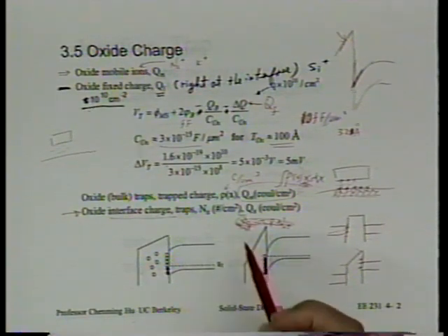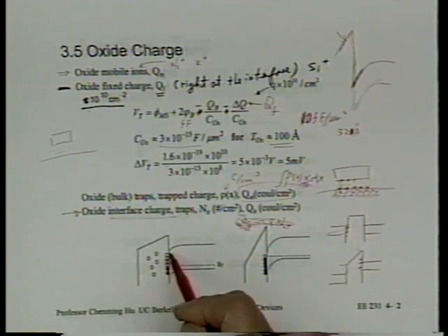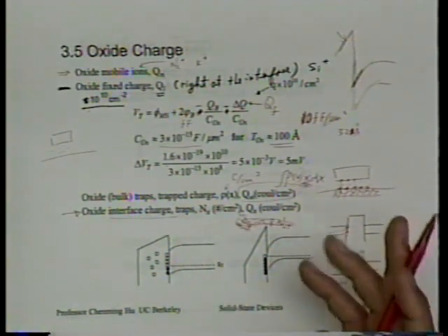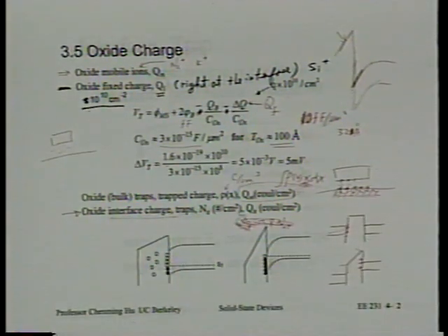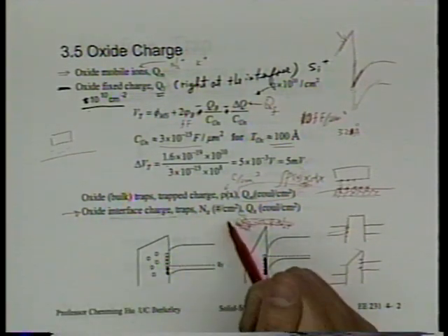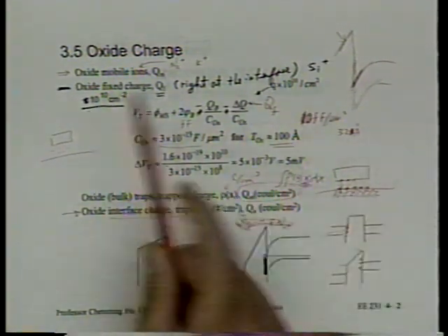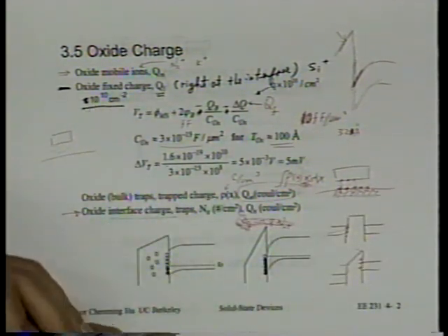The upper limit probably is the number of silicon bonds per centimeter squared. If every silicon atom gives us interface traps, then we'll be talking about, say, 3 to 5 times 10 to the 14ths. Let's say 4 times 10 to the 14ths. All right? That will be the upper limit. It's quite amazing that good oxide can have traps as low as maybe, again, a few times 10 to the 10th per centimeter squared.